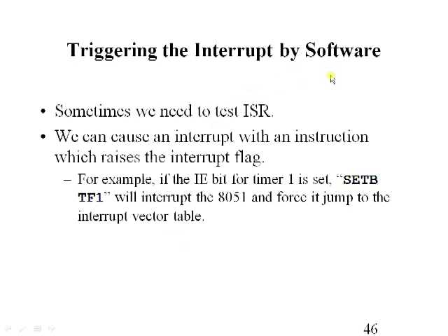Triggering the interrupt by software. We can also generate the same interrupt with the help of software, that is by using the SETB instruction and programming TF1 or TF0 to 1, which will generate a software interrupt.